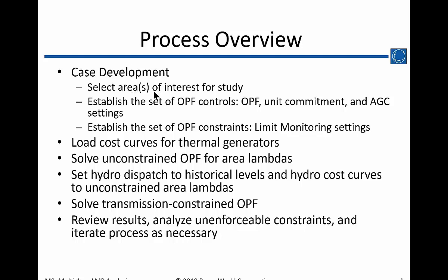But it's good to know what all needs to be included in that so that you make sure that that's part of your process. Often on a very large case, at least in North American cases, unless it's ERCOT, usually you're not studying the entire footprint of what's modeled in the case. You know, in this example, the case will have the whole western part of the U.S. in there, but we're only going to study the California footprint.